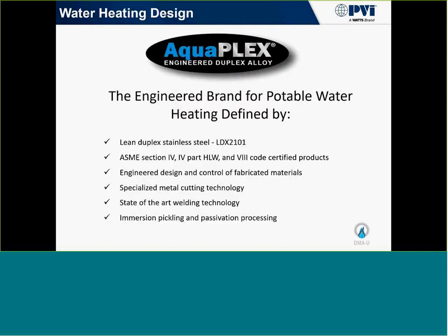So it's specifically designed for potable water. Everything that PVI makes is ASME constructed, and it's specifically designed for the applications that you guys are going to be putting it into. But not only do they have the material, they have the access to the technology for cutting it, welding it, and then, equally as important, the ability to pickle it and passivate it with that hydrofluoric and nitric acid bath.